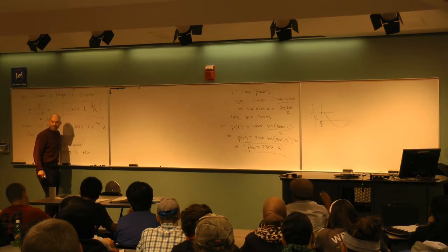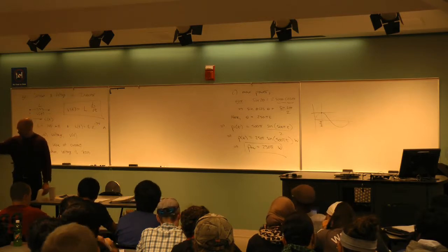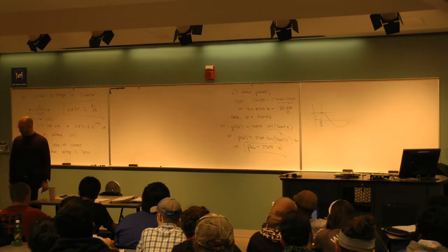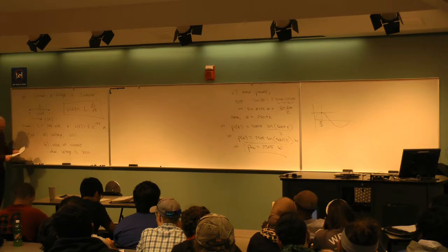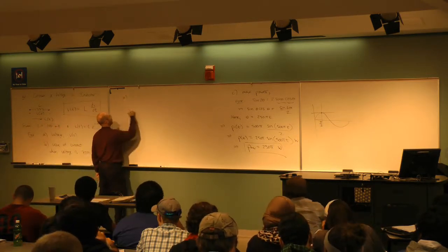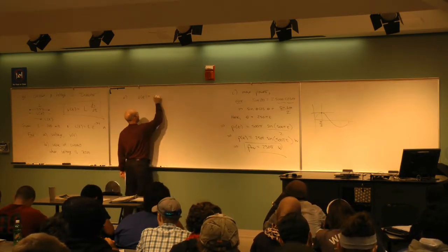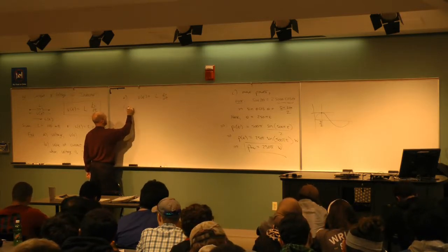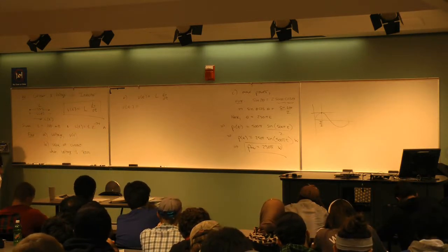Now, if you have no voltage all the time, V equals 0 is a constant, then you're not worried, right? But V equals 0 at one instant in time, maximum current. All right, excellent. So, moving forward, how do I get the voltage? Apparently, V of t is equal to L times the derivative, di/dt. So I know what the L is. L is 100 millihenries. How many henries is that?